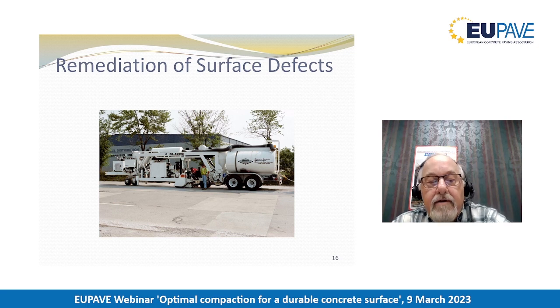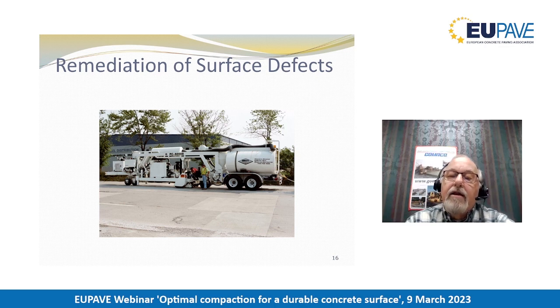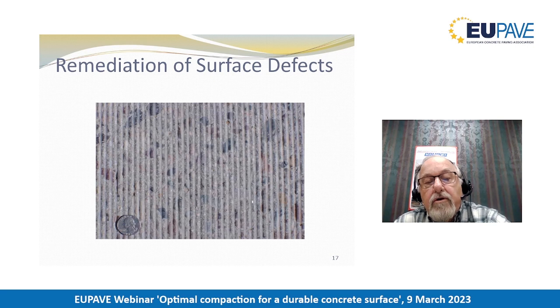If you go back to that picture that we just looked at with that high level of porosity, you diamond grind the surface of that, and because it goes down beyond the limits of what we're going to grind, we just can't compensate for that level of deterioration that we're going to anticipate. So the diamond ground surface looks like this. The question to ask when you're doing an evaluation after the fact is, is that surface sound? Is it still prone to scaling? And is it permeable?